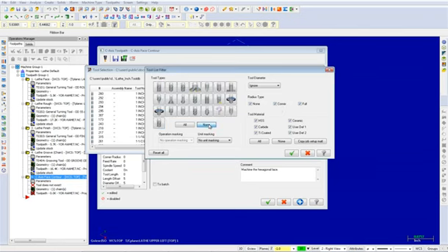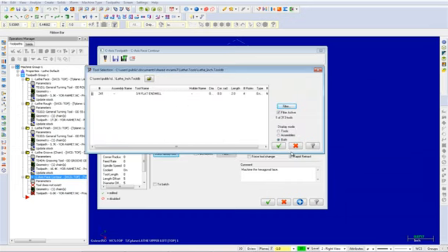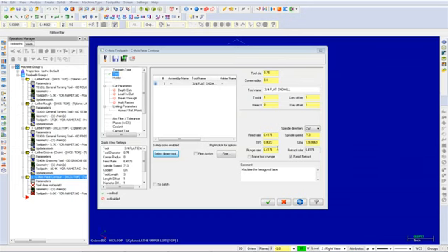Select the None button and pick the flat end mill type. Now, under Tool Diameter, make it equal and input a value of 0.75. Once you have done this, select the OK button to exit the Tool List Filter dialog box. You should now only see a 3/4 inch flat end mill. Select that tool and choose the OK button to exit the Tool Selection dialog box. The flat end mill should now appear in the tool list as shown.